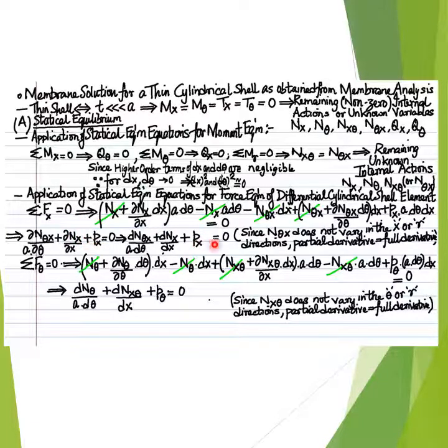Noting that the in-plane or membrane shear force n theta x does not vary in the x or r coordinate directions of the cylindrical coordinate system, the partial derivative of the in-plane or membrane shear force n theta x is equal to the full derivative.